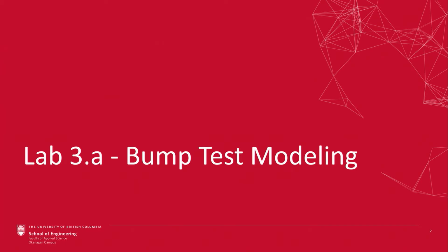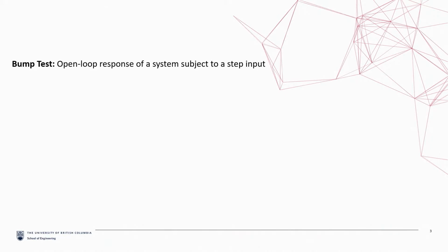So the first exercise in this lab is the bump test. The bump test is basically a simple test based on the step response of a stable system. A step input is given to the system and its response is recorded.